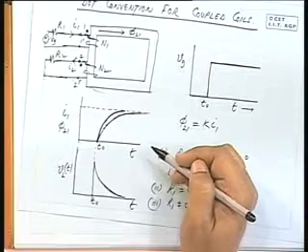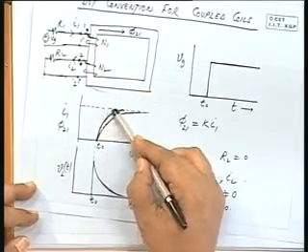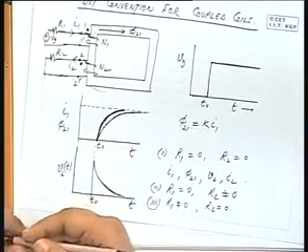Is it all right? Think of the situation in a transformer equivalent circuit, if you have studied already. On the load side, now you are having resistance R2. Earlier it was kept open. Now you are putting a resistance R2. That means in the equivalent circuit you are providing an alternative path through that secondary coil. So the total current increases. Earlier it was only the magnetizing current, now you are offering another path. So the current I1 will have a higher slope like this, and it will reach that value very fast.